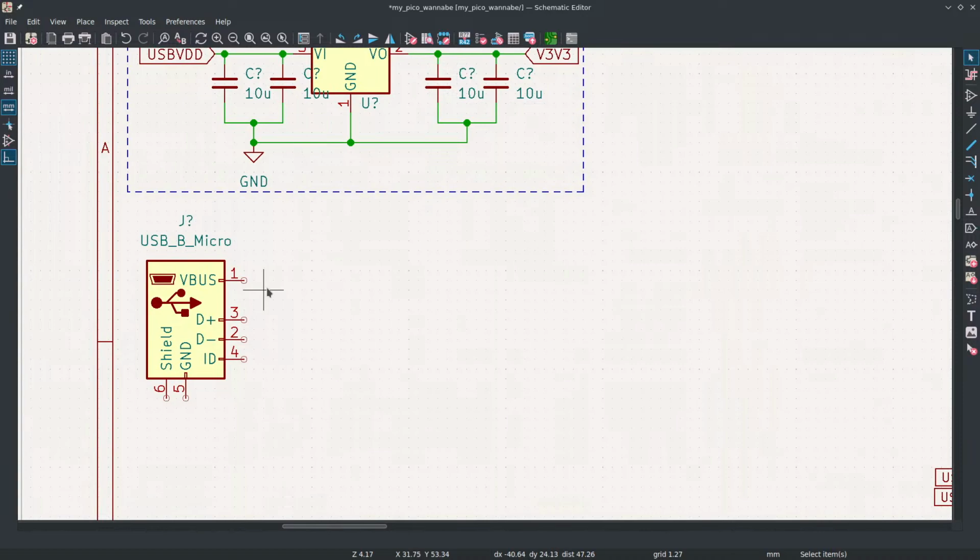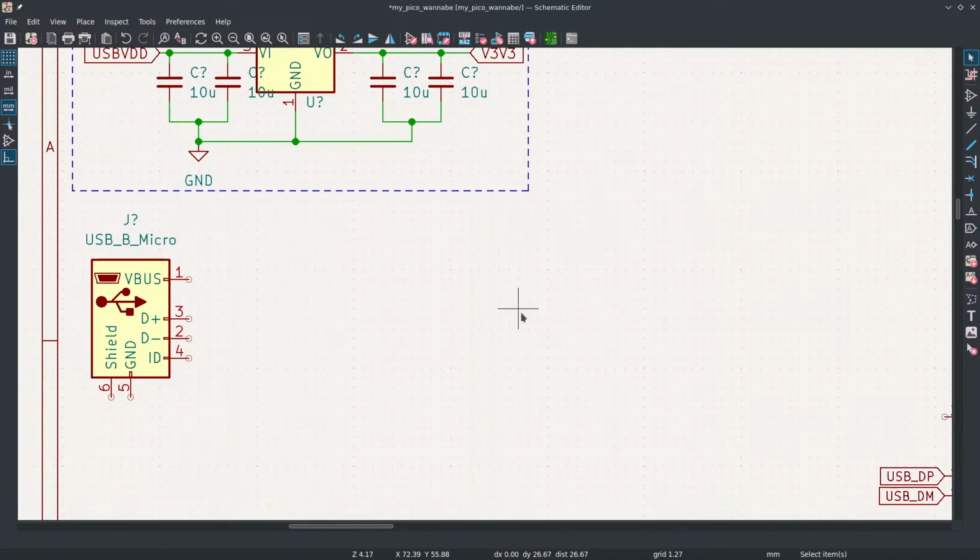Yeah, it's not a big deal if you have a manufacturer that does it, but honestly, when you get tighter density, you're probably going to end up paying more. Like you definitely pay a premium for ball grid array components, which, instead of having a bunch of pins on the outside, have all these balls underneath. They're great for high density, but they're really hard to solder by hand, and you cannot solder them provably right by hand. So it's just a little diversion there.